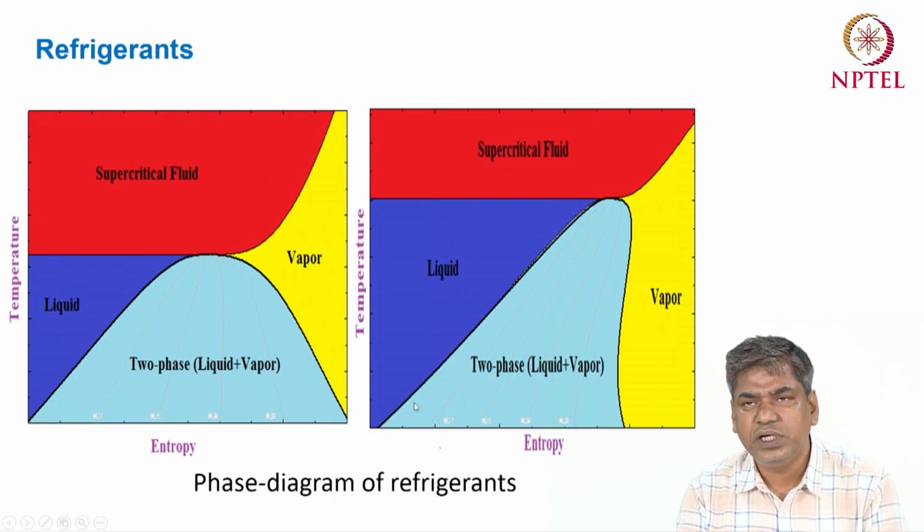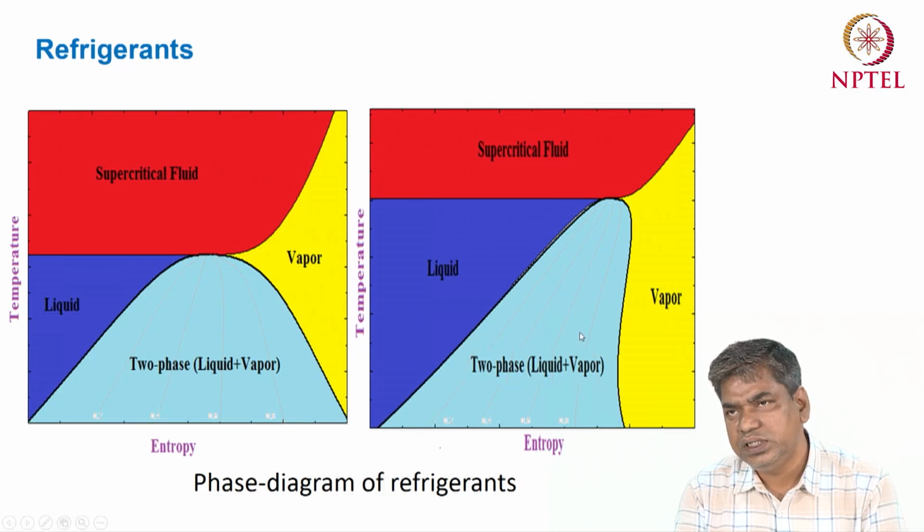So that type of fluid is called the isentropic fluid. For example, if you consider water or ammonia, for this case the nature of the saturated vapor line is just like a wet fluid, that means the first case. So that means ammonia is called a wet fluid. But if you consider isobutane, then you will see that the nature of the saturated vapor line is just like the dry fluid condition.